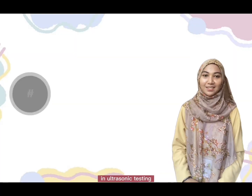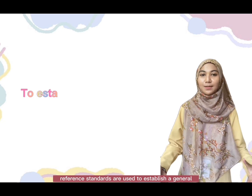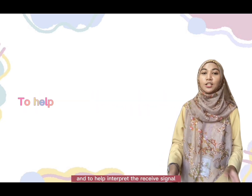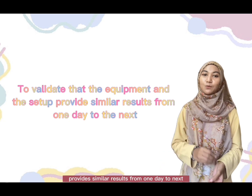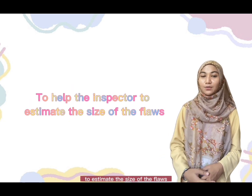In ultrasonic testing, there is also a need for a reference standard. Reference standards are used to establish a general level of consistency in measurements and to help interpret the received signal, to validate the equipment and the setup so it provides similar results from one day to the next, and also to help the inspector estimate the size of the flaws.